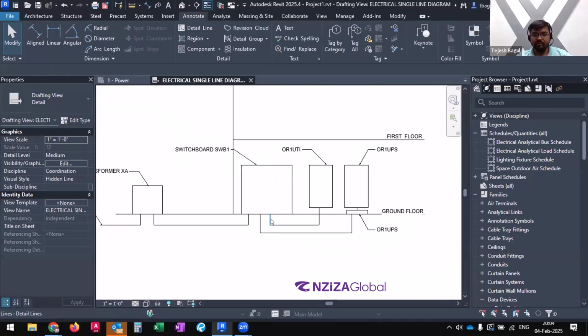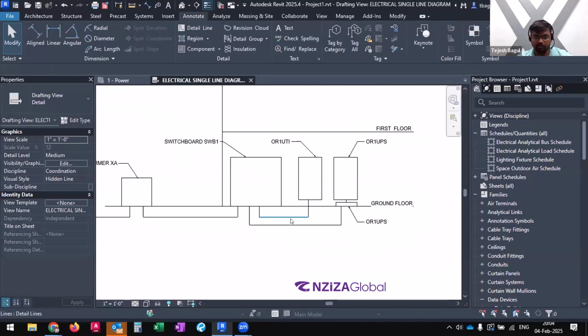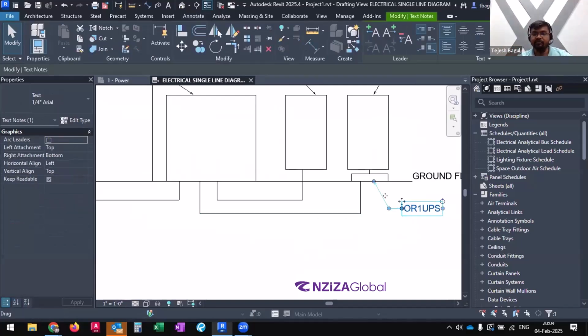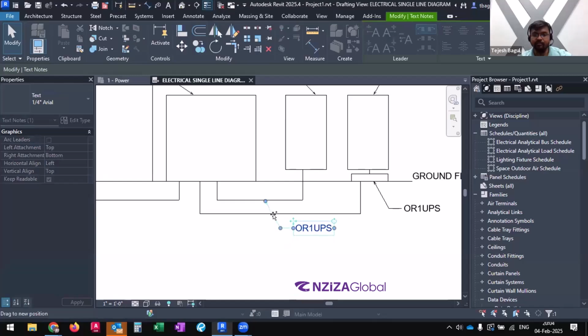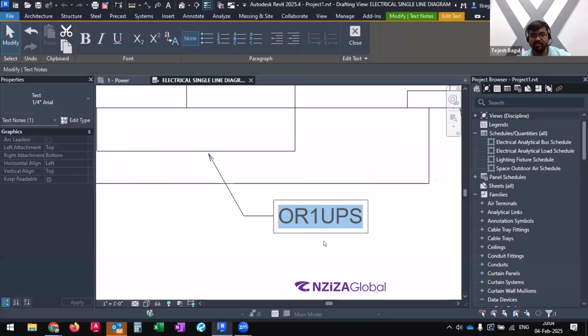Now over here, both of these panel boards, we have selected it for 100 amperes. So the wires coming out from the switchboard need to be rated for 100 amperes. We have seen that there are 4 number 3 wire gauge that we will use in a given conduit, that is minimum 1 1/4. So we will again note this.